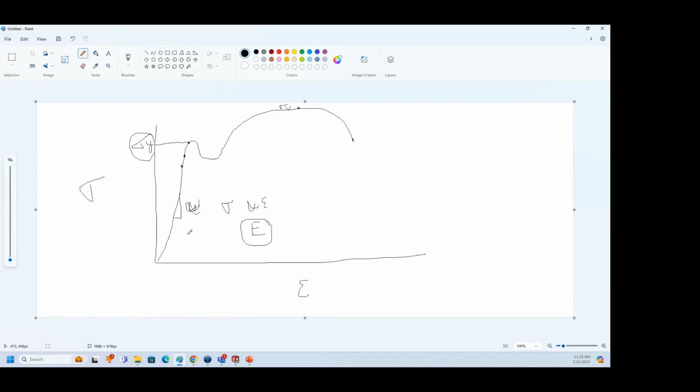Whenever a designer is going to solve a linear static analysis, we know plenty of physics comes into the picture. But whenever I say linear static analysis, the solver is only considering this linear curve up to sigma y. The linear static analysis solver will not consider the rest of this curve. So how can designers come to a conclusion about whether my design is safe or not?